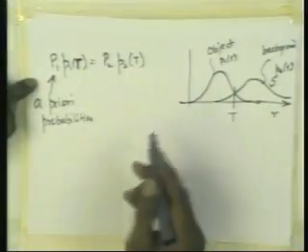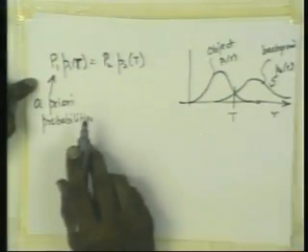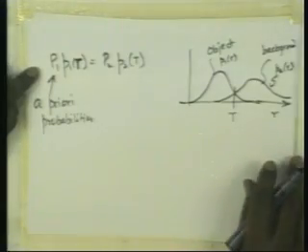Supposing I have a conveyor belt on which some parts are coming, then I know that one part on the average comes every 5 seconds. So, given any scene, I will have on the conveyor belt, let us say, 3 parts. The area of the conveyor belt is so much, the area of the parts is so much. At any given time, I expect 3 parts, which means the corresponding number of pixels at any time are expected to be object pixels, and the remaining are expected to be background pixels. So, if that is the case, then I can multiply these with the probability distribution function of each of the objects, and then I can pick my threshold in this fashion.